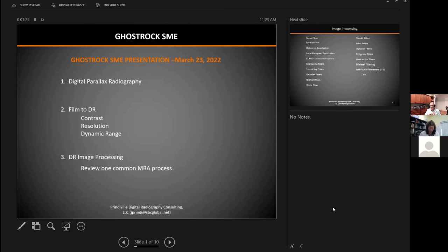In essence, if you follow the spec as written by ASTM, however, it says that if I see the penny hole and I meet the resolution requirement, I'm good to go. Or if I meet the requirement from the compensation principle, I'm good to go. The concern I have with that is when you do this image processing, you're enhancing these spatial frequencies differently, no matter which processing routine you use.